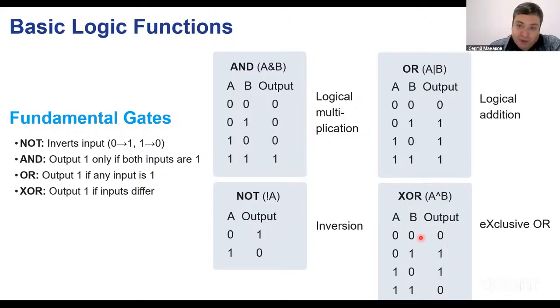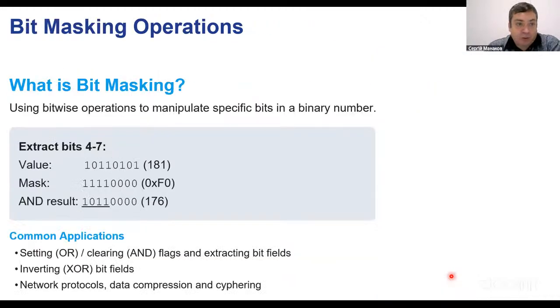Let's apply this mask with XOR to our A number. You see that bits in the mask that contain ones just invert our initial bits. This 0 became 1, and here this 1 becomes 0. So XOR, when used in a mask, has the meaning of inversion and can be used for inverting specified bits.